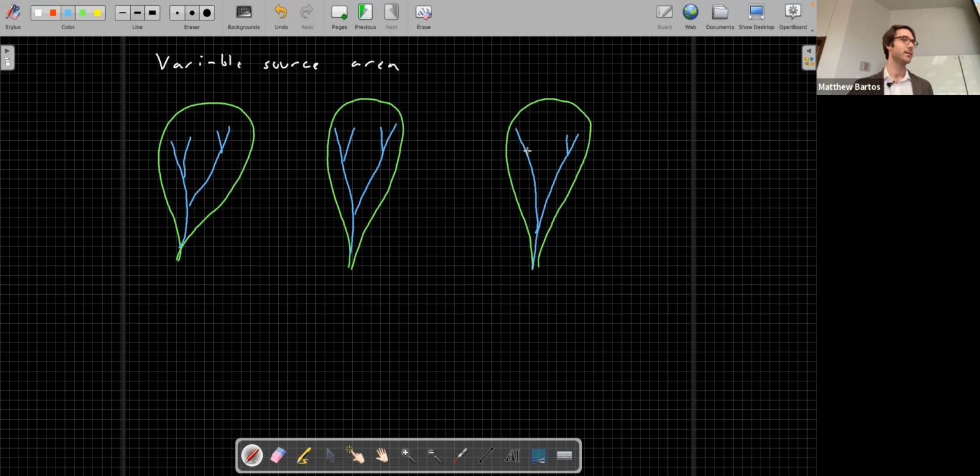What will often happen with saturation excess runoff is that when the rainfall lands on the catchment and starts to saturate, you'll see patches of saturated zone build up around where the channel network occurs. They'll generally stick close to the channel network, although they may also appear in local depressions. You'll get patches of saturated soil, and these patches grow and grow as the rain event progresses. So often in a catchment, you'll get these spatial patterns of saturation.